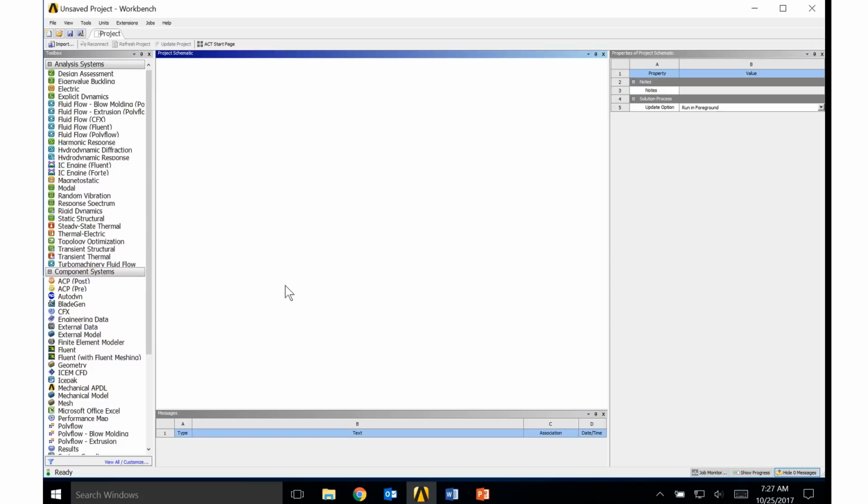Then we'll validate the stresses, the neutral axis, and we'll look at the angle of twist due to the loading. The other thing that we're going to do is scale the entire beam, or the entire cross-section in this case, because the units as they are brought in from a DWG file always come in as metric units, and the American Institute of Steel Construction is based on English units. So to begin with, we will